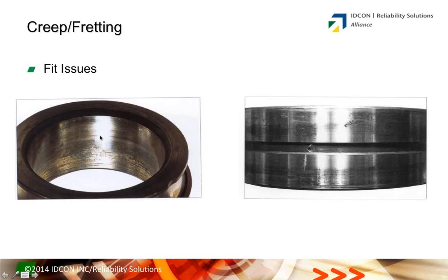One of the most common causes of failure that we see outside of lubrication is incorrect fit. We in North America particularly, but all over the world, do a terrible job of fitting parts together, and particularly installing bearings. When bearings have been installed with too loose a fit, you get a very characteristic pattern. In this case, we're looking at creep or fretting. Very, very characteristic. You can just take a glance at the shaft or the bearing and almost immediately know they had an installation issue right there.